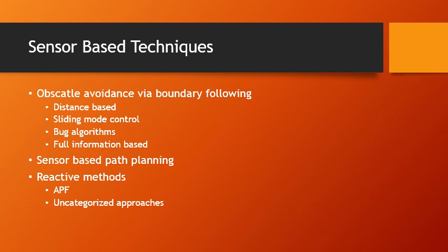Most algorithms establish boundary following in close range as obstacles are encountered. These algorithms do not include any prior sensory information. A reactive control law was established which made the bug type a target-reaching approach for non-holonomic vehicles. Full information-based is when information about the obstacles is available.